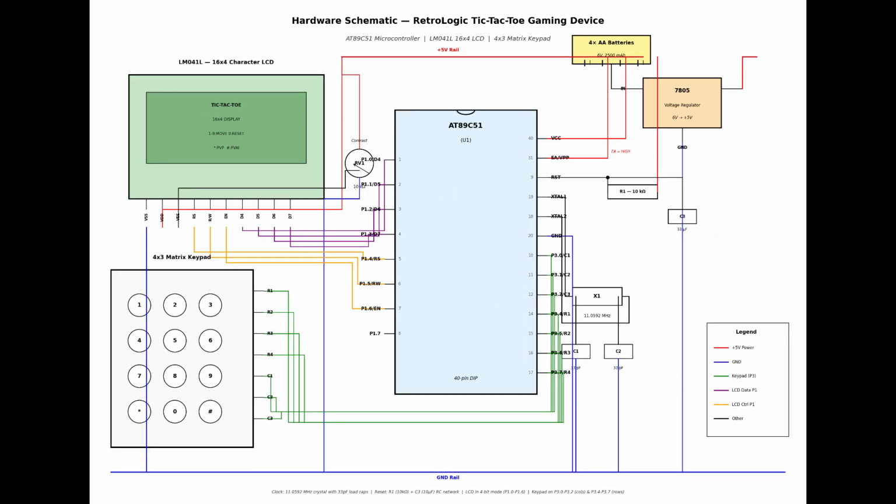While capacitive touch panels require I2C driver ICs, which cost a lot and add much software complexity, a joystick provides poor usability for selecting individual cells in a grid. The 4 by 3 keypad was the clear winner in all three categories: usability, cost, and I/O efficiency.